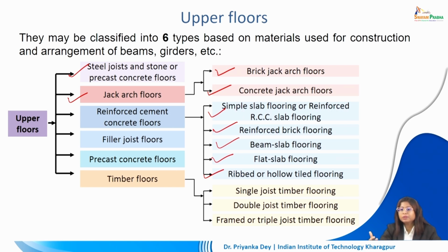by doing away with the excess of concrete in the lower half of the slab, because when we look at the slab cross sectionally, the upper part takes the compression, the lower part takes the tension, and in that case we have the steel bars taking that tensile stress. As a result, we do not really need concrete in that portion. We can actually replace that with the help of hollow tiles, and that, number one, provides insulation properties, acoustical properties. It also helps us reduce the self weight of the slab and the overall reinforcement required in the total slab.